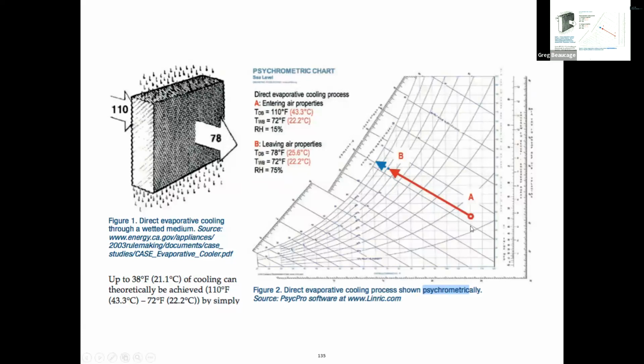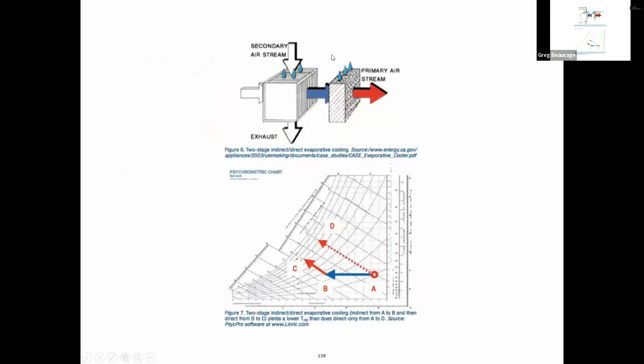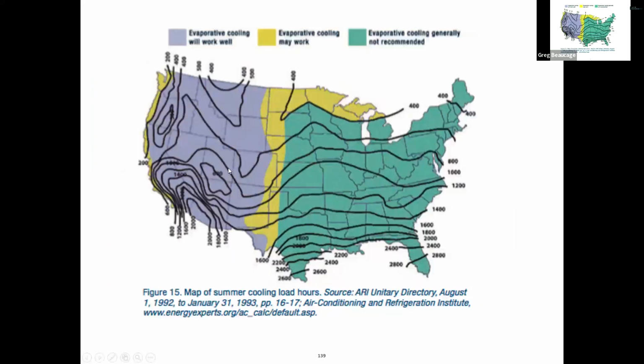And so you're better off being in dry air and at high temperature to get a big gain from this. In other words, that swamp cooler is cooling you from 120 down to 70. That's a 50-degree drop just by blowing a fan over a sponge. If you live in Cincinnati and it's 100% humidity and it's like 80, then you have not as much to gain. You're only going to cool it by 5 degrees. That means these things are only going to work in certain regions. There's a map. Swamp coolers work in that purple part, somewhat in the yellow part. So a little bit of West Texas and then all of the mountain states and nothing around us. You can't use it here.